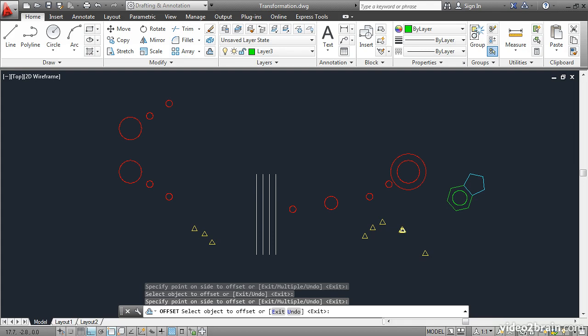You can also offset polylines and circles, splines, and so on, just by selecting them and clicking outside or inside. I'll offset this triangle, which is a polyline. The form remains the same, but the size changes. So in summary, you now know how to manipulate objects freehand, or by using measurements, or with object snap relative to other objects. With practice, you should be able to transform objects into any position, orientation, or scale that you desire.